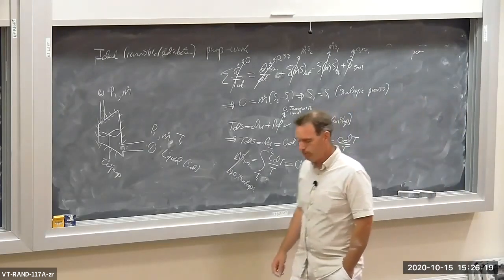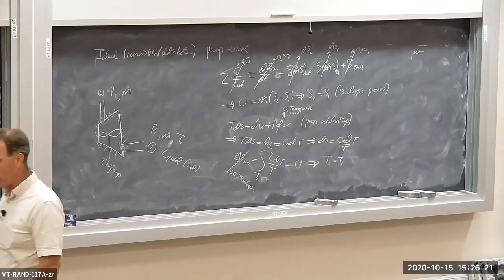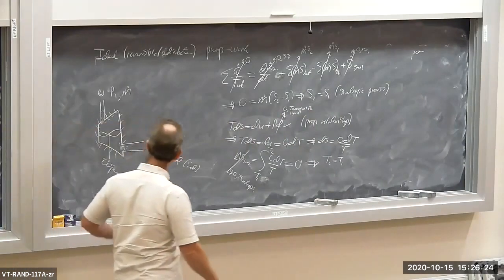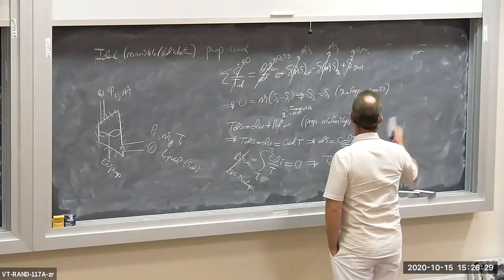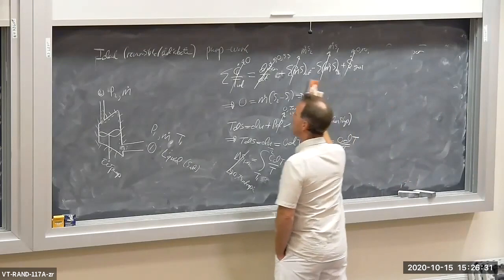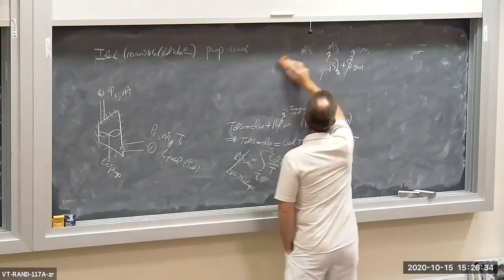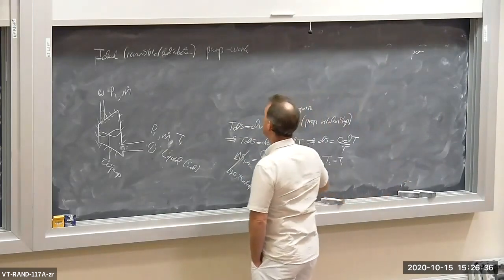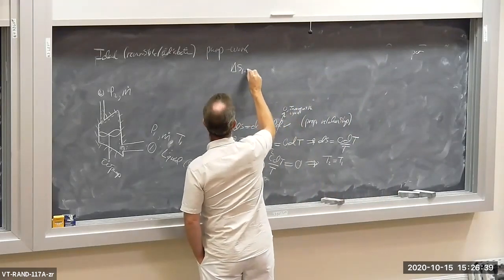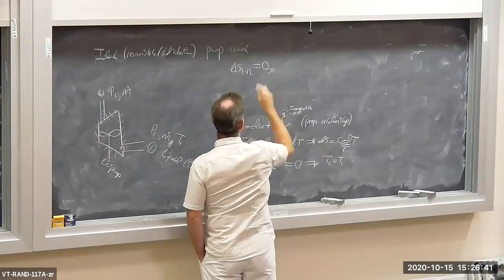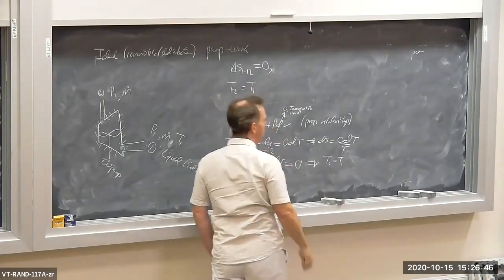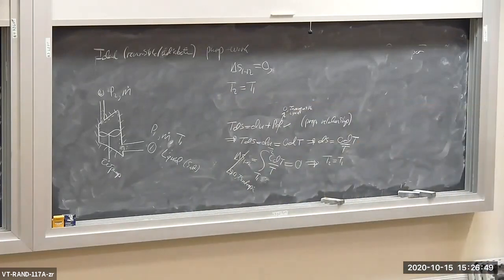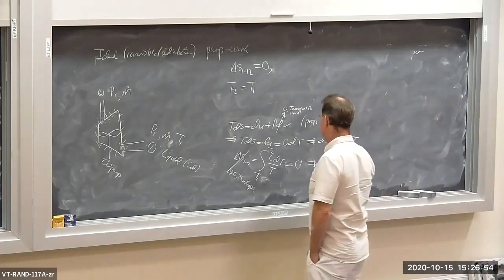So for adiabatic reversible pump work, there is no temperature change from the inlet to the outlet. So isentropic process. So we have delta S from 1 to 2 is 0. And we have, strictly speaking, T2 is equal to T1, strictly speaking, if we have no change in volume whatsoever in our pump.